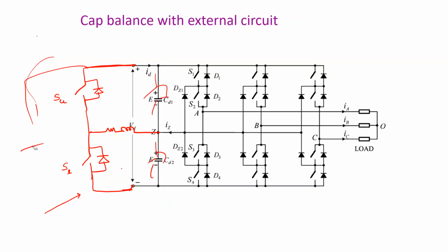That is similar to your H bridge. The cascade H bridge is there. The H bridge and the 4 quadrant chopper are both the same circuit-wise, but the operation is different. Remember that. How we control the firing pulse matters. In an inverter, all the 4 switches are operated together, whereas in a chopper only 2 switches are operated, or modulated. This entire thing forms a 4 quadrant chopper.